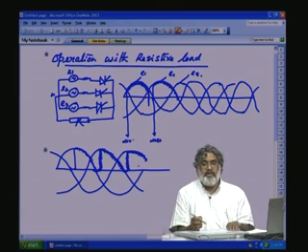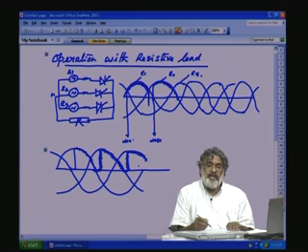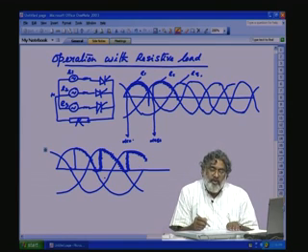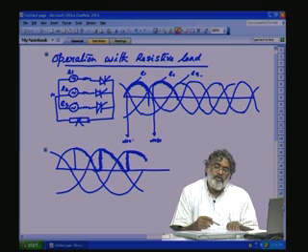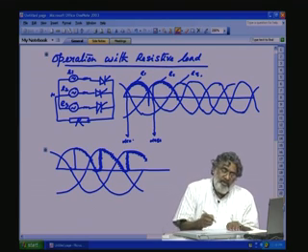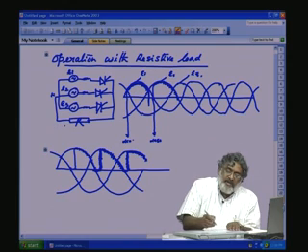Now, see, is it only possible with resistive load? Can we have discontinuity occurrence with an inductive load? It is possible. That means, when the voltage waveform goes negative, we should give an alternate path for the inductance, so that instead of forwarding the thyristor and the current flowing through the thyristor, it can free wheel through another path. So, it is possible. Suppose the load is inductive. See, if you give a diode like this,